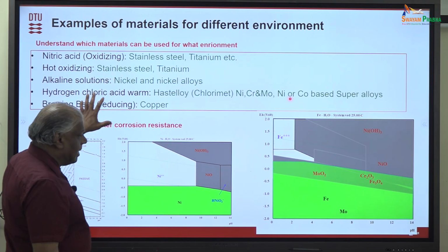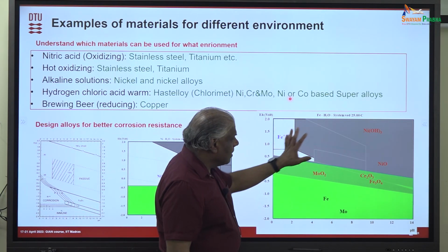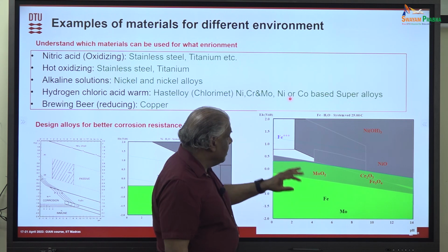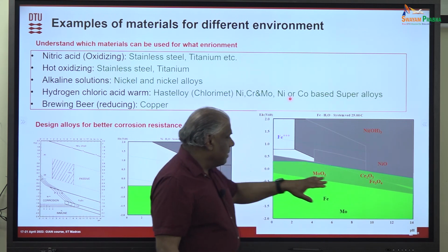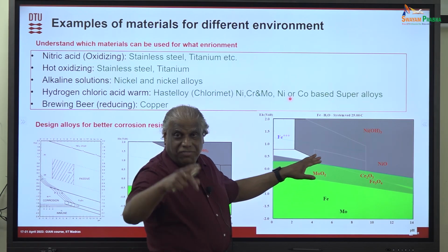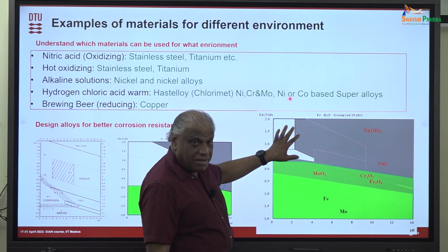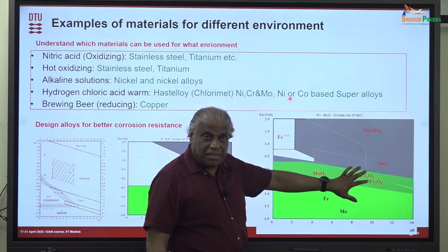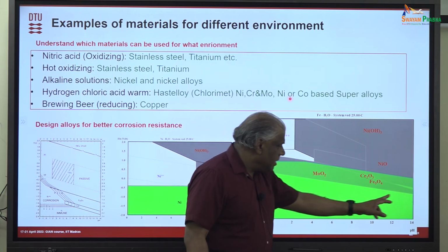But if you look at, again, which we also discussed in the class earlier, the stainless steel, what I did here is put the Pourbaix diagram for iron, the Pourbaix diagram for nickel, and the Pourbaix diagram of molybdenum together. Earlier, in the afternoon, we were discussing that iron has a corrosion region at many places, and chromium oxide is stable in this region,